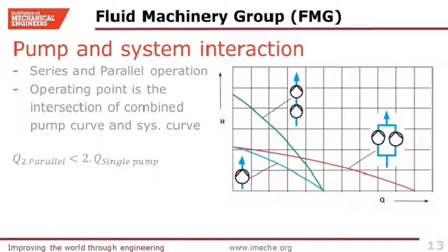So sometimes it's just easier to have identical pumps, because if one of them generates more head than the others, it will push the other pumps back on their curves towards the shutoff. API 610 is asking for a 10% head rise from rated to shutoff for parallel operation.